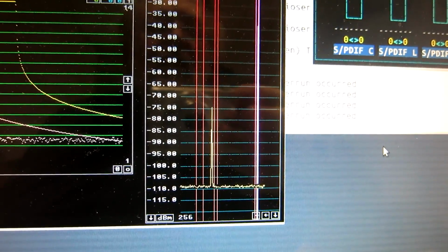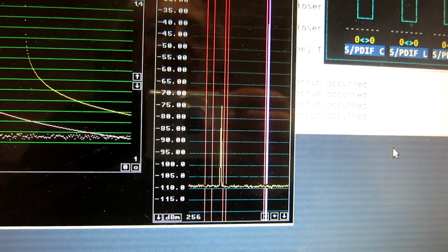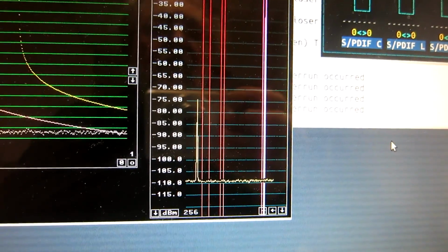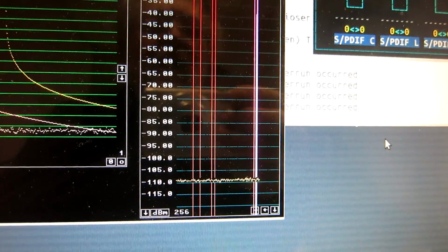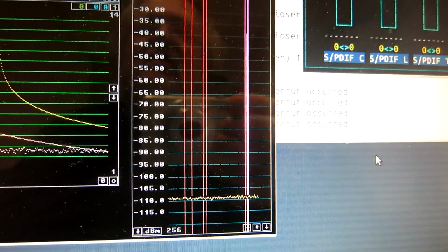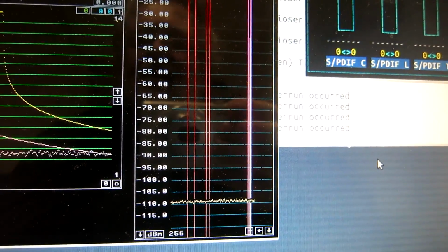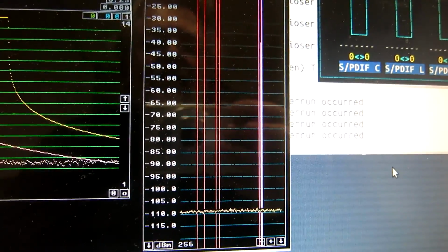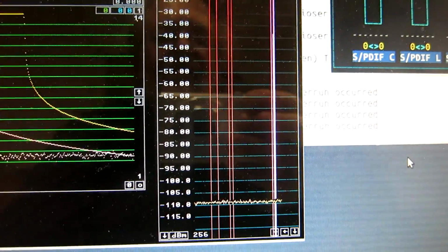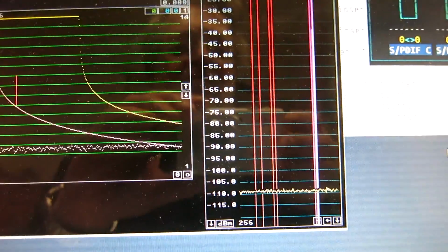These Sound Blaster cards, Creative cards, typically have several gain controls after each other, and it's important to set the right one to avoid saturation in front of the ADC, like we can have in this driver. But getting a driver working in Windows again doesn't mean anything.